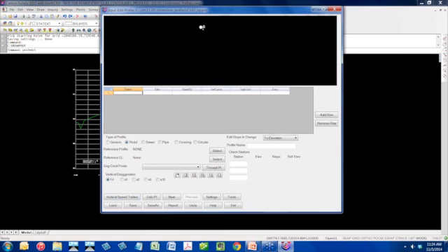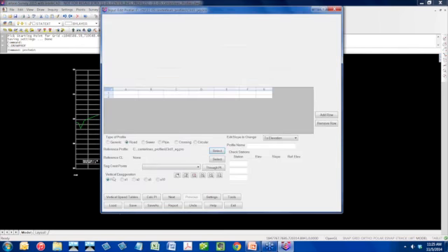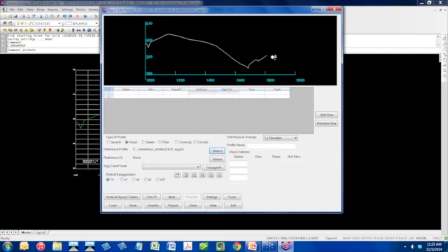All right. So if I know what my station, elevation, everything is, I can just put it in here. But it may be helpful because I have that existing ground surface, that profile I've already created, just as a reference. I've got an option here. I can go into reference profile, select, and just select that existing ground. Now, it just shows up in the background. Notice I can't move my cursor along and it doesn't read the elevations or anything like that, but at least I can see it. The type of road profile is going to be a road.